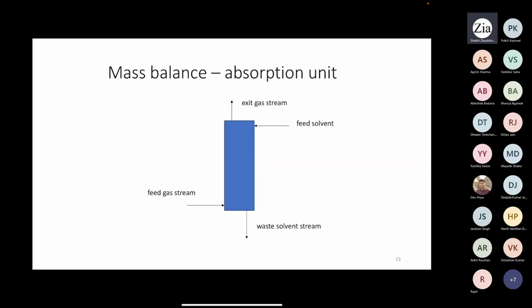And then finally, to desorb that particular component, you either manipulate the operating conditions, like raising temperature or changing pressure, or add some other external solution to remove it from the adsorbent and regenerate the adsorbent surface. So this adsorption unit is also used in the purification stage, that is downstream process, or upstream process, wherever you need to separate two different fluids, whether gas separation or gas liquid separation.